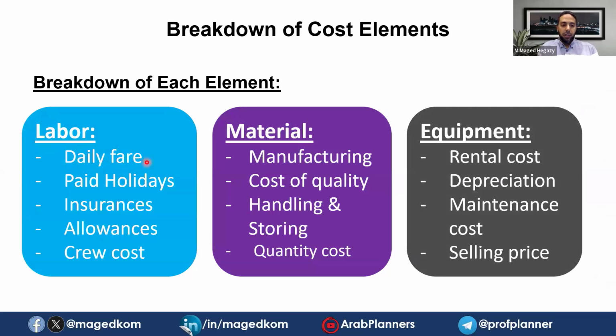So it's not only the daily fare or the salary they are getting. They also have paid holidays. We need to consider that they have insurances, allowances, crew cost of helpers, and all this team working together. So while we are calculating the cost of labor, we need to consider everything.